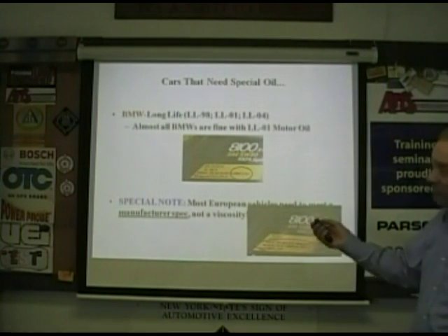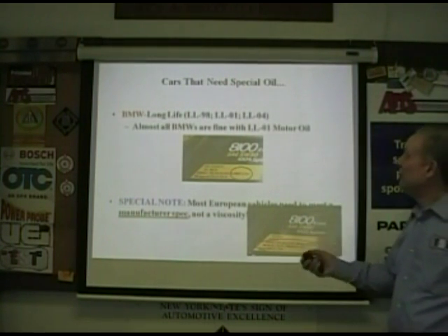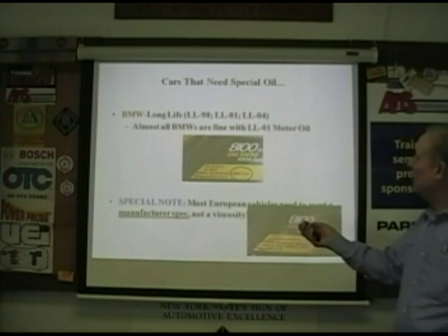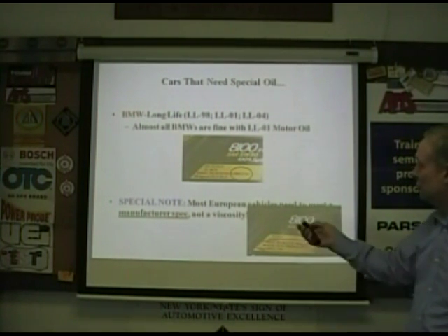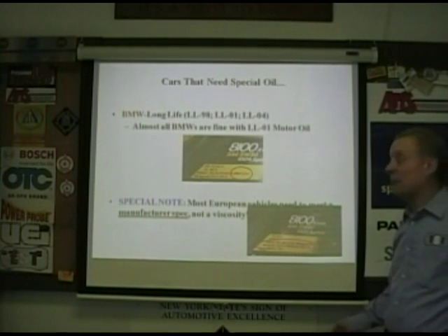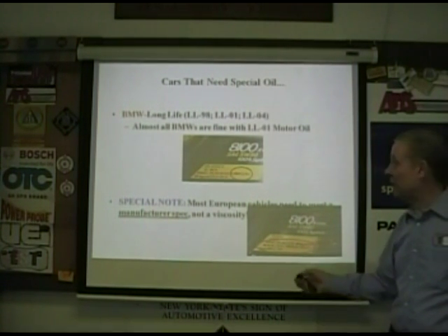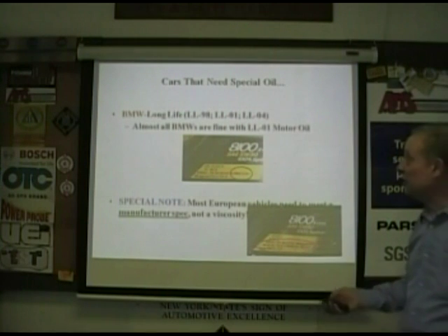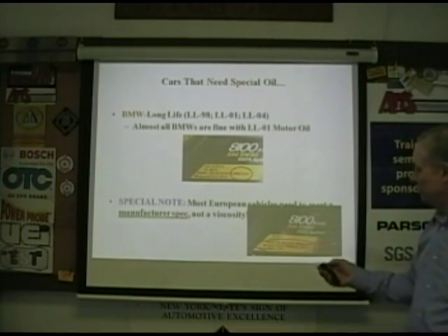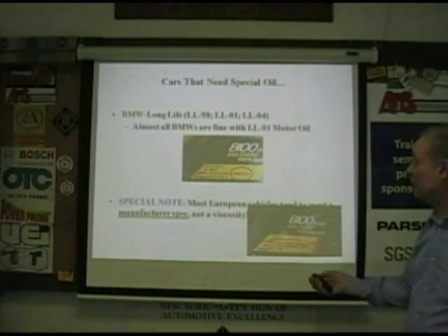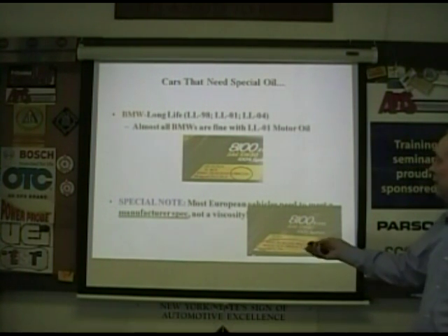Speaking of BMW, they have long life spec, LL-98, 01, and 04. What they don't show here is for their M motors, they also have a special spec for that. It's not on here. M motors need a special oil, 10W60 special oil. Again, read the specs for the particular car you're working on.